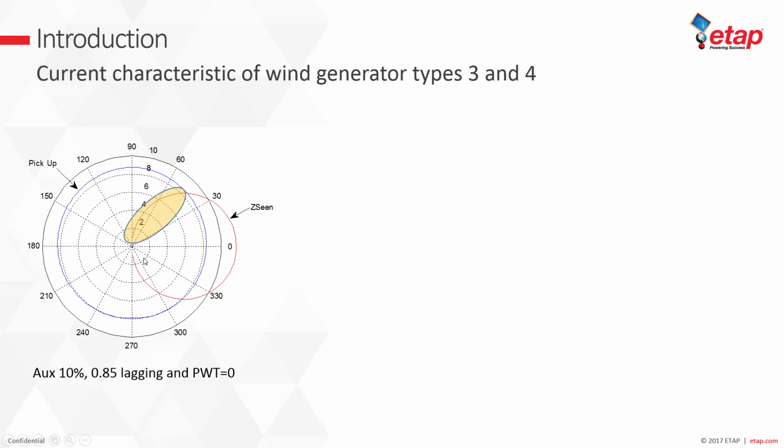So this means that if the typical directional relay is between -30 and 120, this region is not any danger. For angles close to within that range, the current is less than the pickup value. As the current becomes more than the pickup value, the angle is way below that 30 degrees.